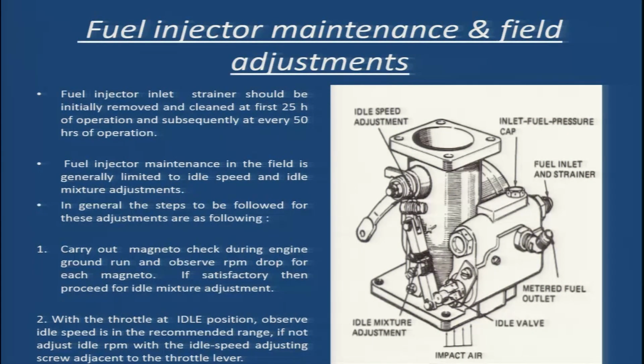Another maintenance and field adjustment on the fuel injector is generally limited to idle speed and idle mixture adjustment. So, basically on the injector, apart from doing visual inspections and checking the unit for satisfactory installation and any loose connections, we can only do idle speed and idle mixture adjustments. Let us see what are the steps when we do these adjustments.